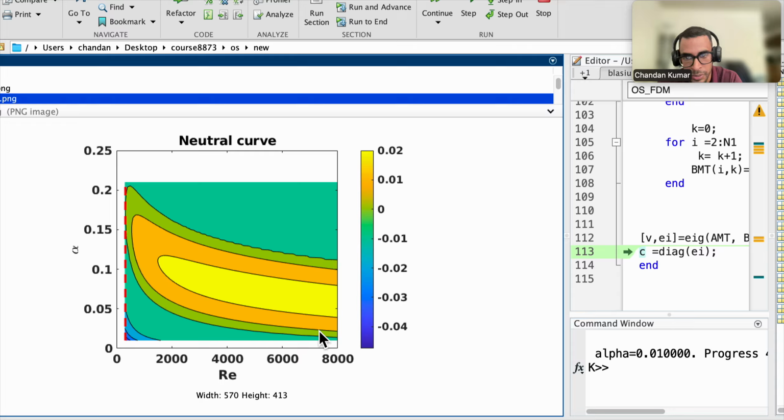It continues downstream, and over the range of the Reynolds number. The critical Reynolds number does not indicate that transition will happen at this location, but this is the location where the instability begins. If it stays unstable, over time it saturates and its amplitude may grow or decay. If it keeps growing, it will lead to transition. If it decays, it won't lead to transition. So this is very informative.